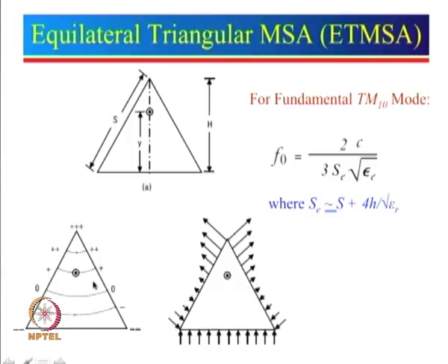So, that also determines how to choose the feed point. One can look at the distribution for this particular feed point. Now, it does not always mean that you have to feed here. You can also choose, let us say, an axis like this. If you choose an axis like this, then the null will be somewhere here and you need to feed along this one here, or you can think about rotating this triangle by 60 degrees and that will change the null location.